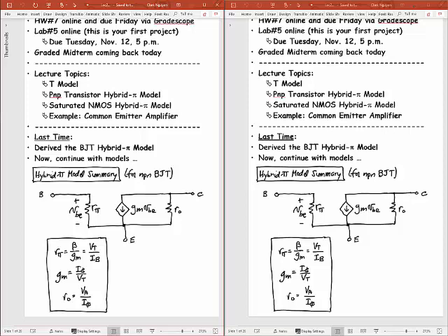This is just for small signal here. And I think I'll make that very clear when I do the example small signal analysis. But right now, this is only when you have a small signal coming into the base. You may have a larger signal on the collector, but we're using small signal because, again, the transistor is a nonlinear device, and so we can only put tiny signals into the base. And we'll talk about why it's okay to have large signals going across the collector.